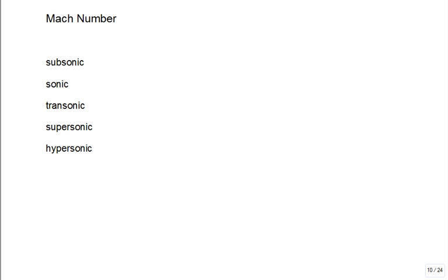Mach number. So we use Ma in this textbook for the Mach number. If the Mach number is really small, less than 0.3, typically the compressible effects are neglected. It's treated as incompressible. Even air. Unless you really start moving air, a lot of times you can treat it as incompressible.